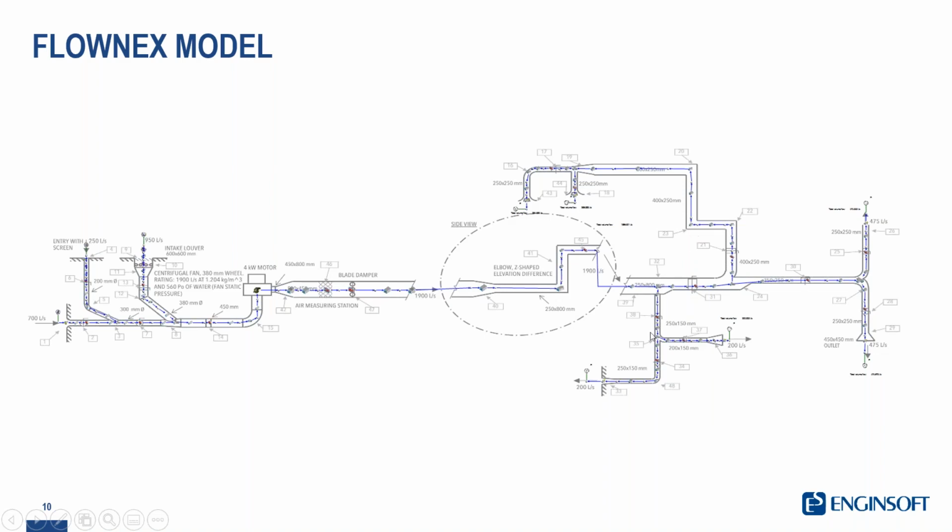So you can put a lot of components and connect them together to represent the real diameter of each part of the system, and you can put the fan or blower, and then you have the dampers, and then you continue with the distribution with the louvers and all the channels. Then you can put a boundary condition to represent the exit, an atmospheric boundary condition, and you have the possibility to set the boundary condition also in terms of humidity. So if the fluid flow is humid air, it is a mixture of air and water, and the content of water generally represents the relative humidity.